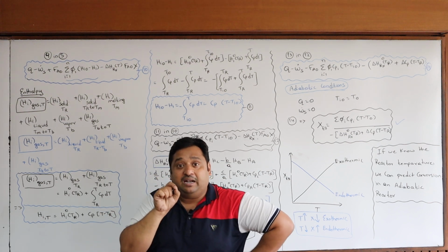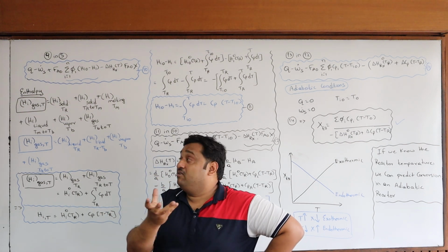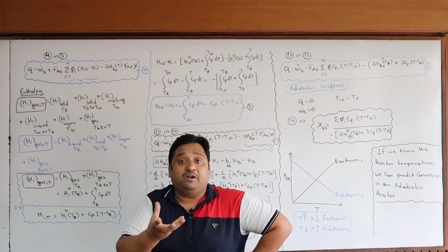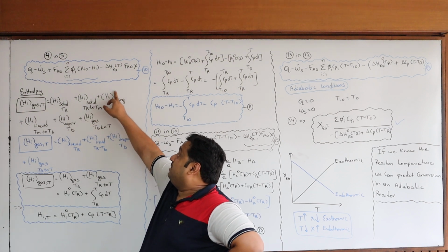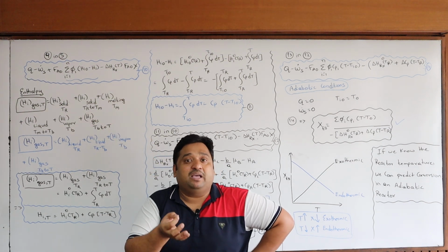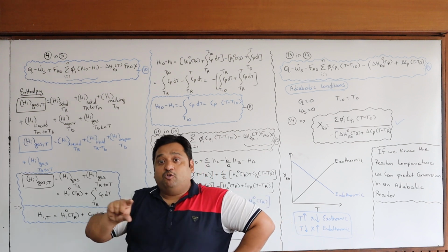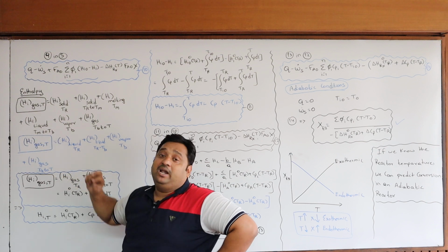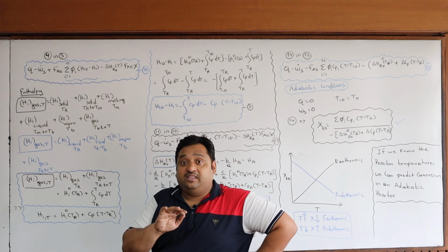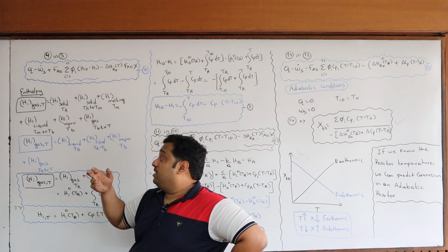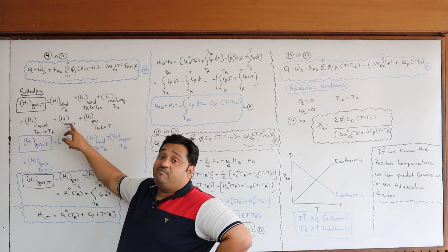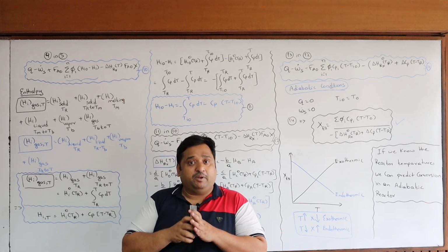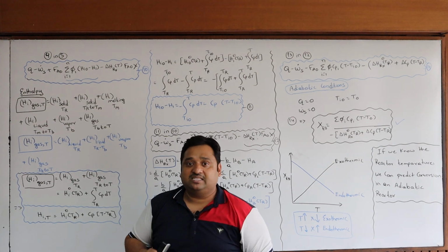Okay. At that melting point, what is going on? Latent heat of melting. During the melting process, some heat is required. So that is the enthalpy of melting. From melting, that means it has become a liquid state. From the liquid state, it goes to the vaporization state. That means the liquid is heated from the melting temperature Tm to the boiling temperature. At the boiling temperature, the liquid will become gas or vapor. Then you have to add the enthalpy of vaporization. After vaporization, you need to heat again, because now it has become a gas at the boiling point.